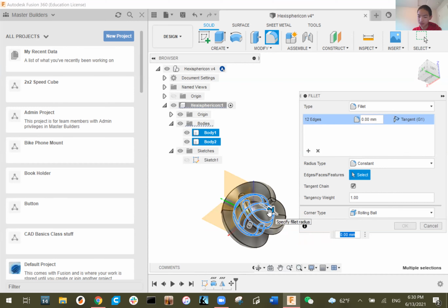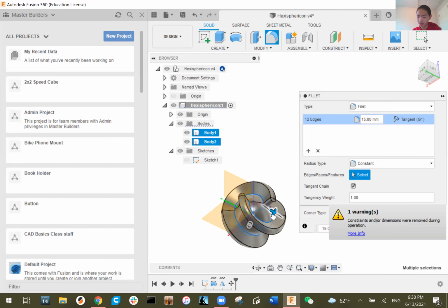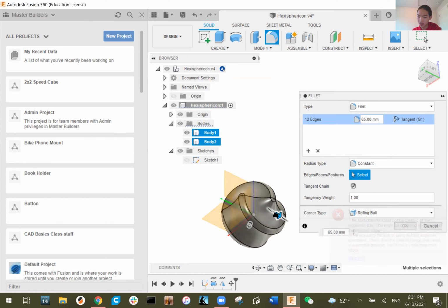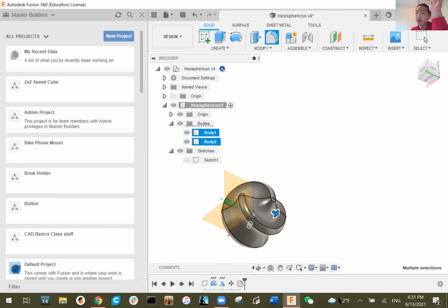So now what you can do is drag the arrow, and you can see that it connects all the edges, and now you have a smooth surface. You can drag it around depending on how much of the space you want to fill up. That's by your preference. But now you can see that it creates a smooth inner layer, and so I'm just going to do it at the minimum, so that's 40, and then enter.